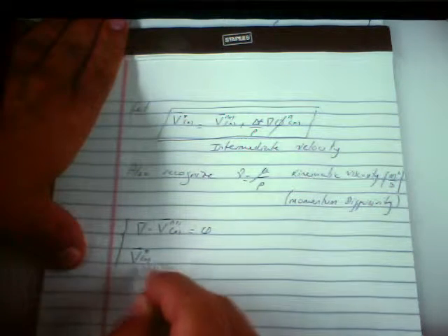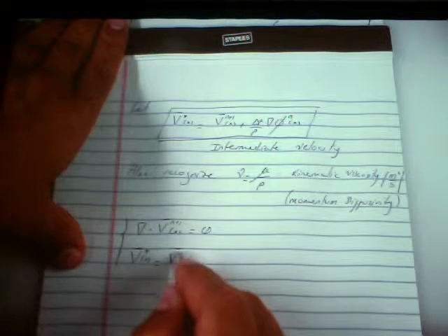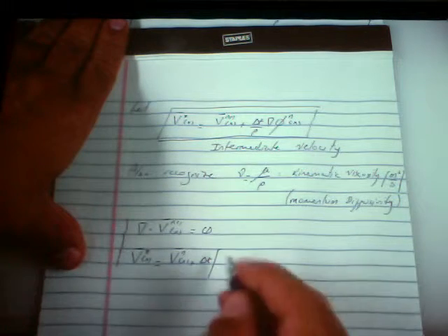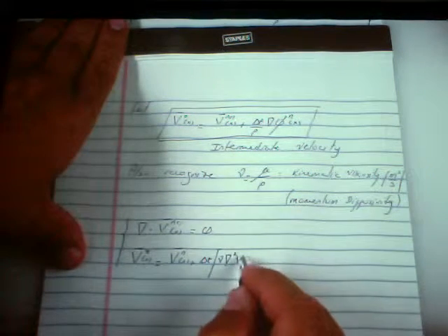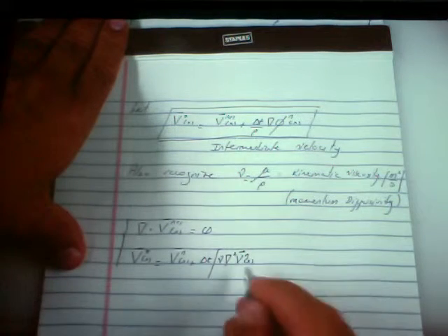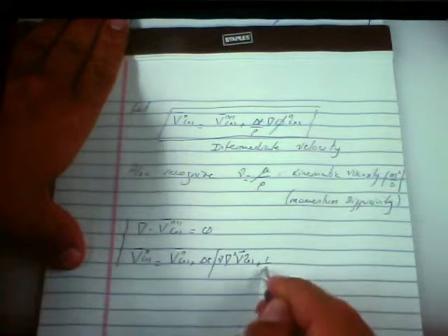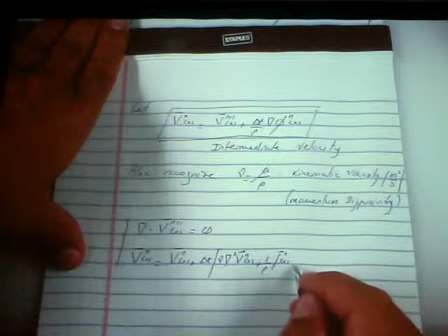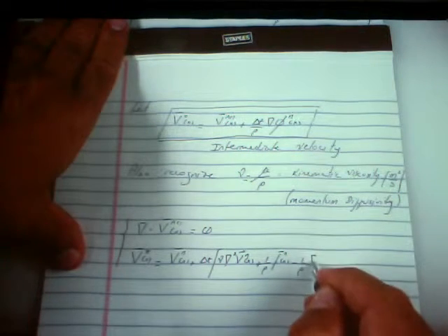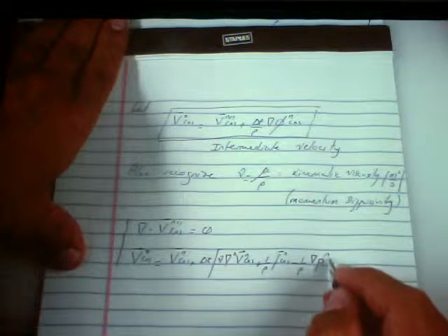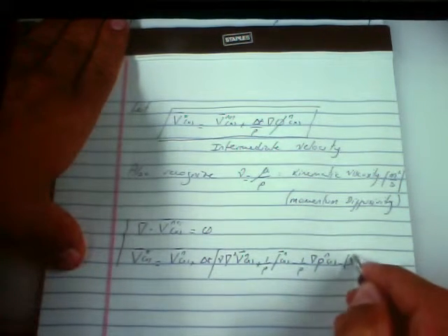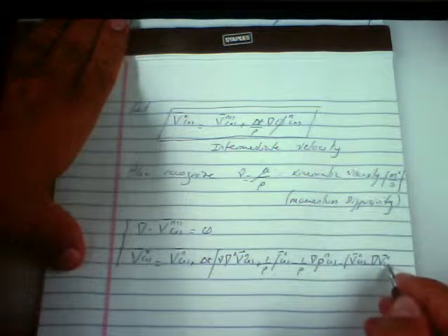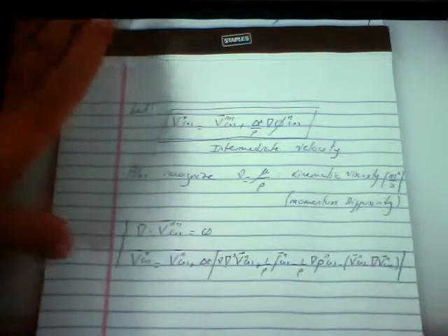It's V star, which is equal to V at n plus delta t times nu Laplace of the velocity, plus 1 over rho forcing term, minus 1 over rho gradient of the pressure, minus the velocity dotted into the gradient of the velocity. That's the Lagrange derivative of the velocity.